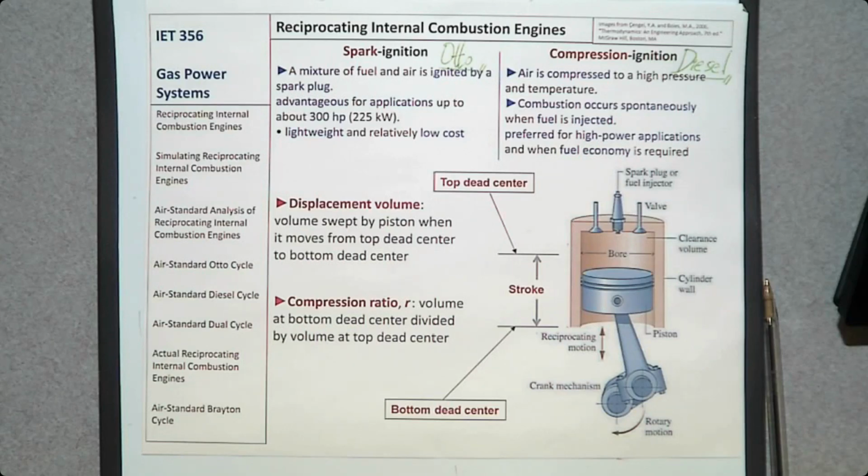It's not an advantage. Then what is the problem of this diesel engine? You need to compress this air as high as possible. Now you're going to inject fuel at extremely high pressure and extremely high temperature. Do you think it's going to be easy? No, it's not easy. So that's why usually diesel engines are more expensive than gasoline engines.